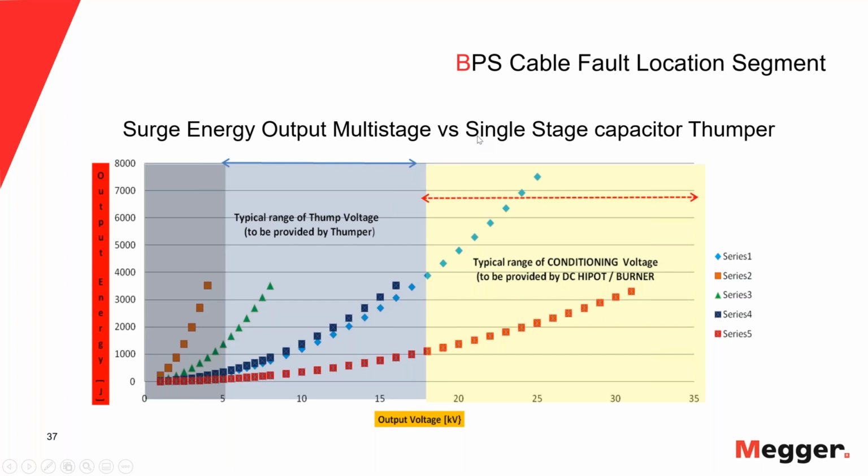Normally people say, well, I don't want to really go much beyond 10 kV because it's only 13.8 and it's old, and I'm concerned I thump this cable to death, because you might have to thump for a longer time. It will take some time to fault locate using this method.